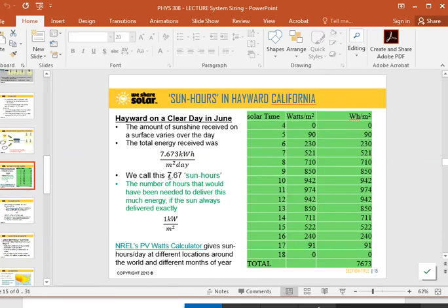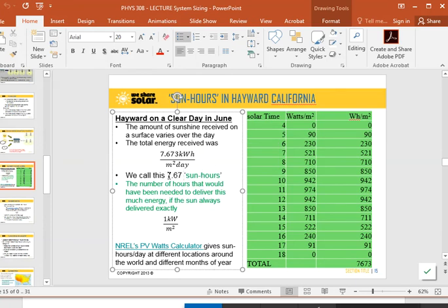So that's basically like saying if this is, let's just say, 8 sun hours, that says that a day is as if the sun was directly above for 8 hours, right? So it's taking all the complexity of the sun rising, going behind the clouds sometimes, but sometimes not, and we're reducing that all down into one number. Every day is as if the sun just hovered directly above for 8 hours, right? In this particular case. In your case, it may be different.